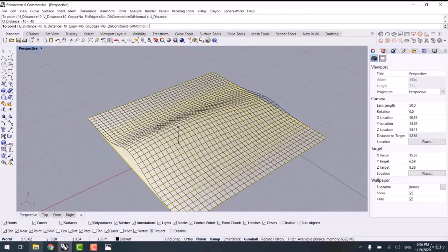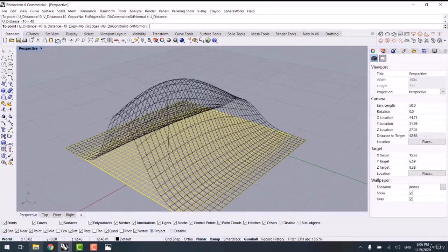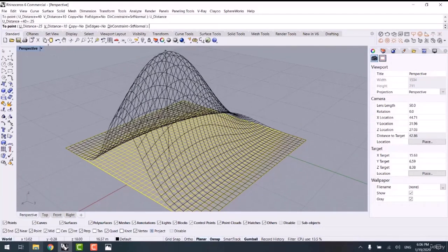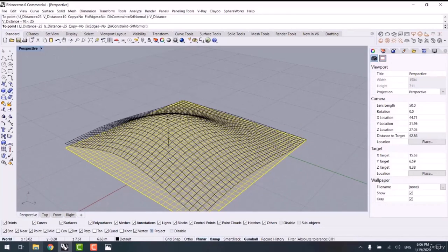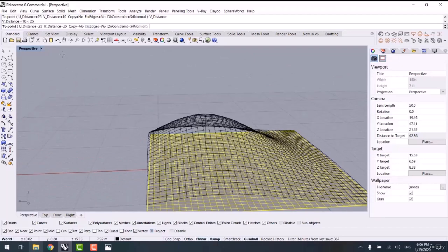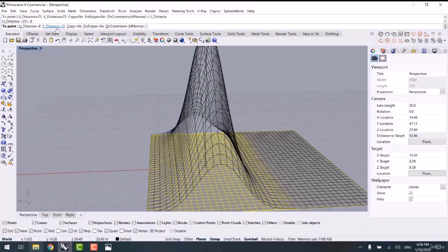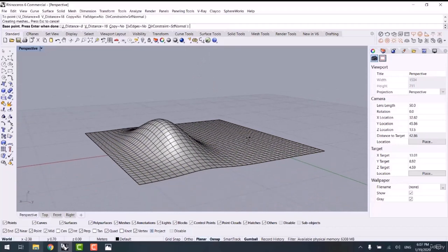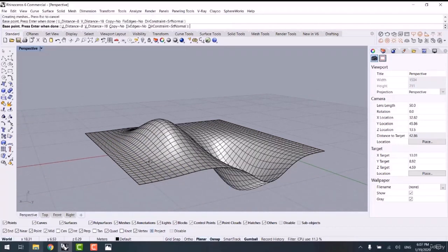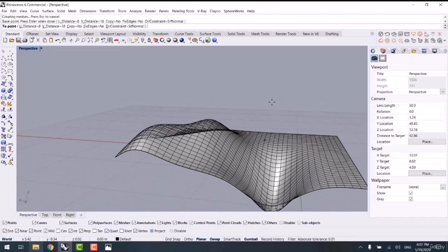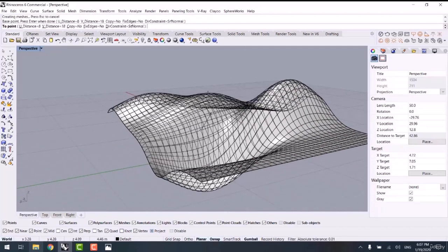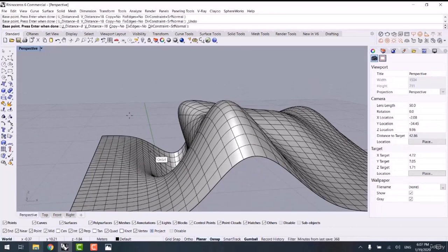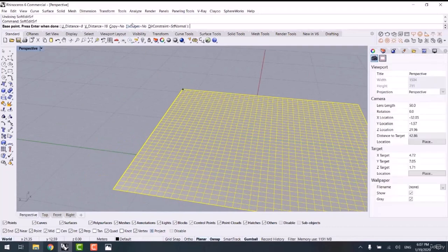As you can see, it moves the surface at both U and V distances. If I set it to 25 and 25 for both U and V, 8 and 18, check it out. So the typed distances will be influenced in the U and V directions when we move the point. And here we got an option which is fix edges, which has been set to no. Let me adjust the distances.